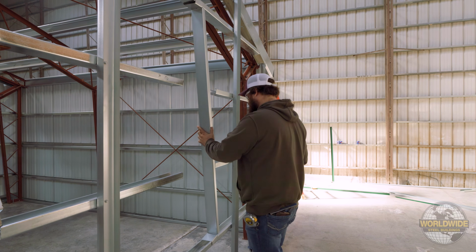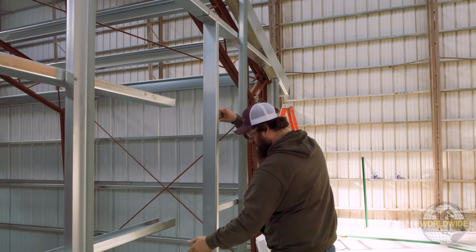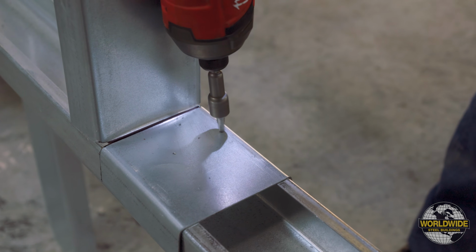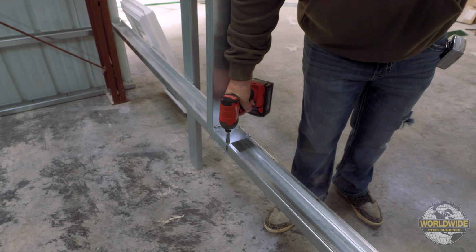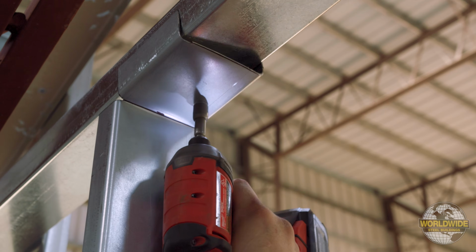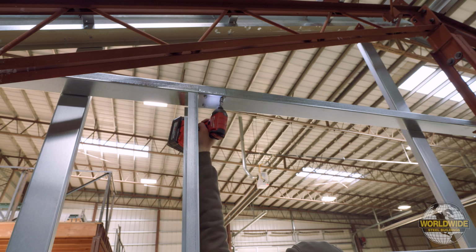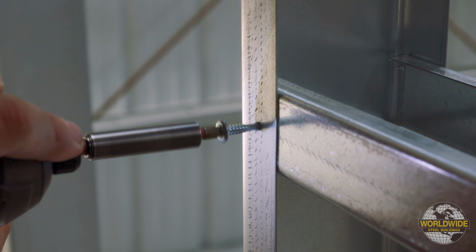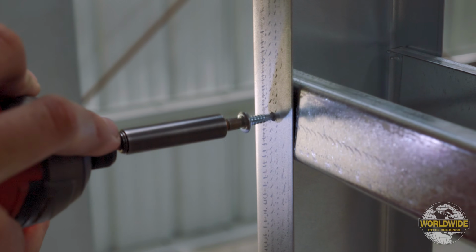Place one jamb inside the opening. If you have cut a girt, it will slide inside the track as shown here. Attach the jamb at the bottom tab using 4 Tek screws. Then, ensuring the jamb is plumb, attach the upper tab using 4 Tek screws. Using pancake head fasteners, attach any girts to the jambs as needed through both legs of the track.